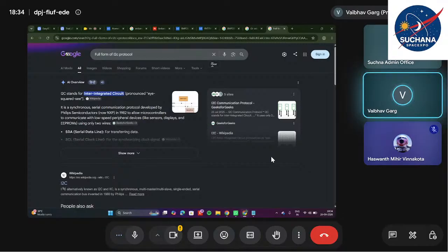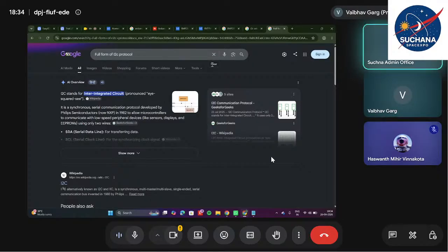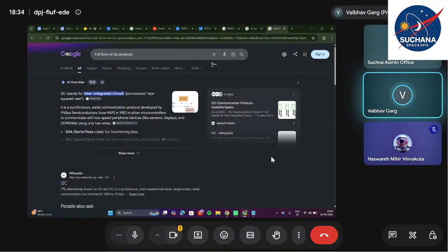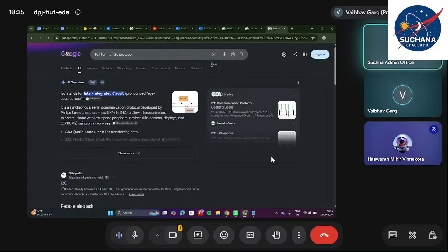Okay. So why do you think the engineer has enabled such an option to switch between I2C addresses? So that we can function multiple things on it. So let's say I will tell one thing. I told that only with the help of the I square C address, a master or else a microcontroller is able to differentiate whether the data is coming from sensor A or sensor B, right?